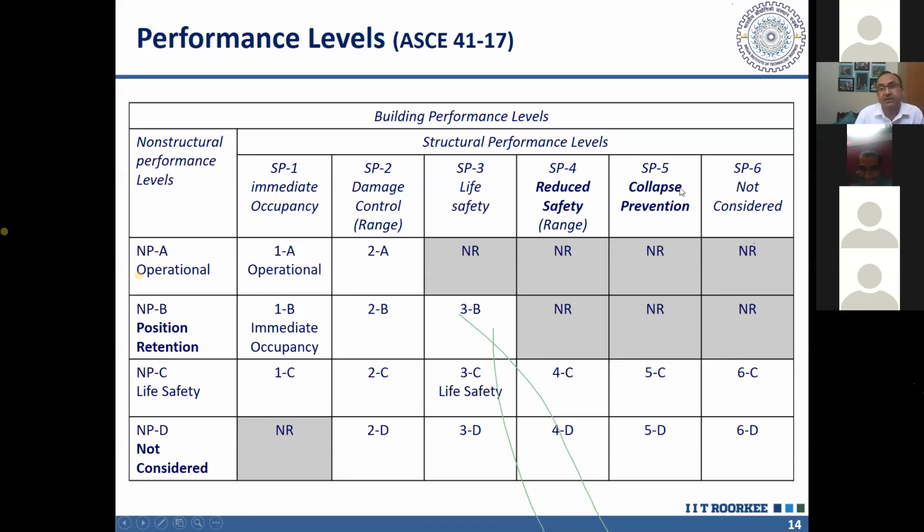You may be frightened by this scenario, that the building which you are designing as per code is designed in such a way that some fraction of the occupants will die if that MCE earthquake occurs. But keep in mind that it is a very, very rare phenomenon, and the forces are very large, 10 times of what we are designing for. So we take advantage of this rarity of the phenomenon, and we design for lower forces.